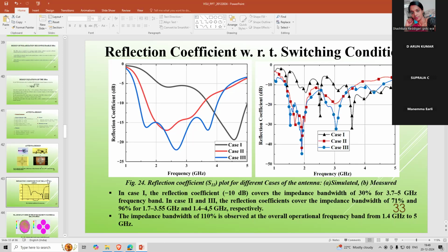For the biasing circuit, you have to check two things, width and length. We have to consider 0.03 mm. If you change that value, there will be some variation in performance. Accordingly, the proper inductor should be connected on the biasing line. That value you will get from the data sheet. All those things you have to check. Once the simulation gives proper performance, then you go for fabrication. Thank you, sir, for the information.